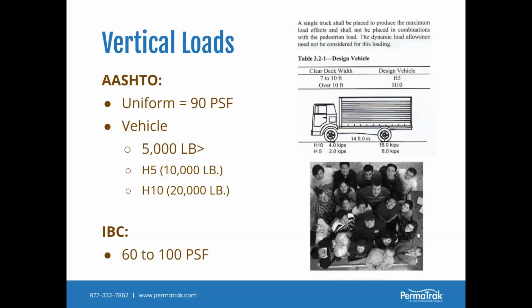But let's look at the vehicular loading. If your boardwalk is 7 feet or less, and this is coming right out of the pedestrian bridge guide, there is no requirement for a vehicular load. Now, standard practice has been to design it for at least what you would expect to go over a very narrow boardwalk. I would expect a small Gator or some light vehicle to go over the top. So we would design a boardwalk for no less than a 5,000-pound Gator running over the top, which is really a heavy Gator.